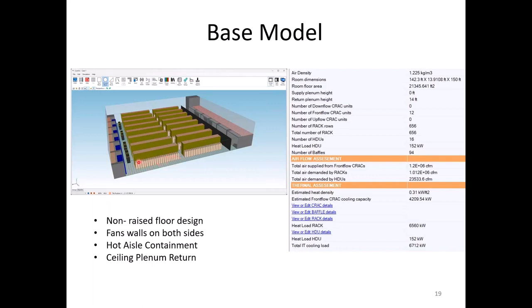You see the racks here on the front. This is the containment here. It's got a ceiling plenum return back to the fan coils. These are what generally are referred to as fan walls. It is the entire surface of both sides in this case. I've seen them with one side, I've seen them with both sides. In this case, both sides are dumping heat into this room.